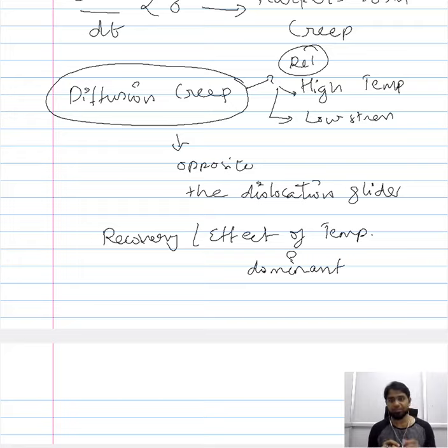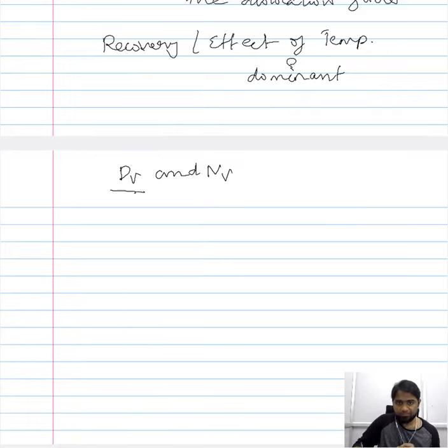We explained the creep mechanism in the preceding discussion based on the increase in the dislocation density, when it was concerned with strain hardening. Now we will see how the dominant effect of the temperature presents itself. One factor that directly relates to the temperature is the diffusivity of vacancies and the number of vacancies. Now these two factors are directly dependent on the temperature.